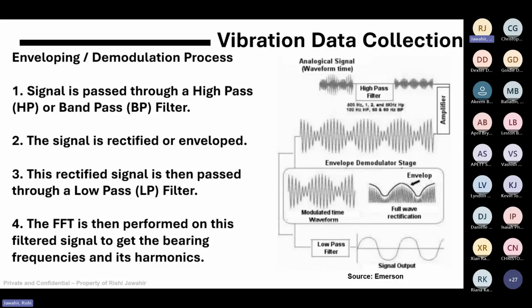Each technology has a different spin on it, but basically this is what it entails. It's a signal processing technique. It's a filtering technique that uses high pass and low pass filters to filter out the unwanted vibration and gives you the actual bearing defect frequencies for you to perform your diagnostics, right?